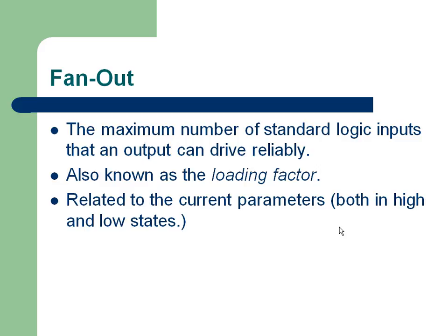Now let me also tell you one important thing. When it comes to ASICs and also FPGAs, we use one word called clock tree. Clock tree insertion, clock tree management, clock management: these are the important phases in ASIC backend. Of course, in the front end also there are some directives. Through your VHDL code, you can give directives. Through your coding style, the tool will automatically figure out what is clock, what is reset, etc.